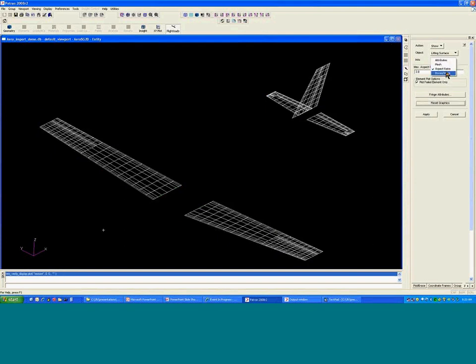And then the other one that's for unsteady aerodynamics in particular is important is this Nyquist criteria, also called the boxes per wavelength criteria. It's basically how many boxes in the chordwise direction to capture the oscillatory aerodynamics effectively. And there's a couple of different ways to input the data, but generally you can input it in either physical dimensional units or in non-dimensionalized units. So I'll stick with dimensional. And in this case, I'm going to say my minimum velocity of interest, say for some flutter solution later on, is about 4,000 inches per second.